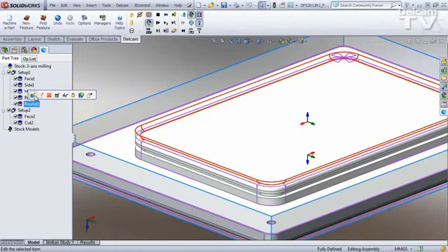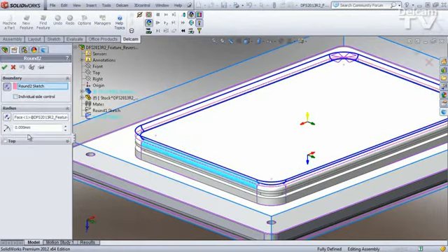Just click on this, go to the feature. The reason this is upside down is that because we're using a sketch, this feature depends on the normal of the sketch plane to determine the tool axis direction. If that's upside down, your feature's upside down. So the way we'd fix this in the past is pick a different sketch plane, and sometimes that involved creating more planes, and then maybe inverting one of them, and it was painful. Sometimes you'd have to create an axis in order to invert the plane, and it was really painful.